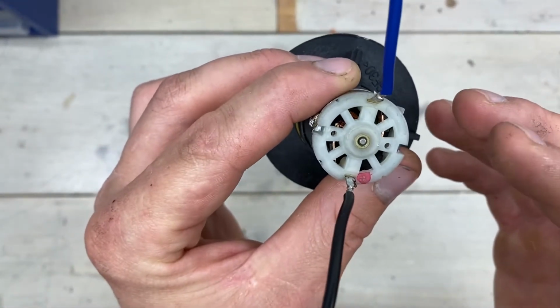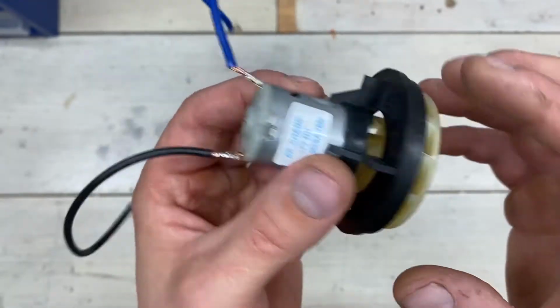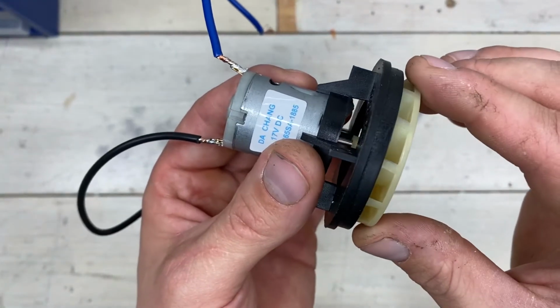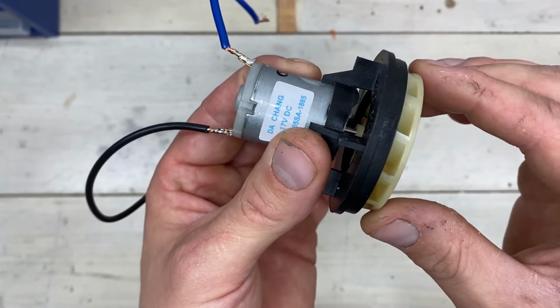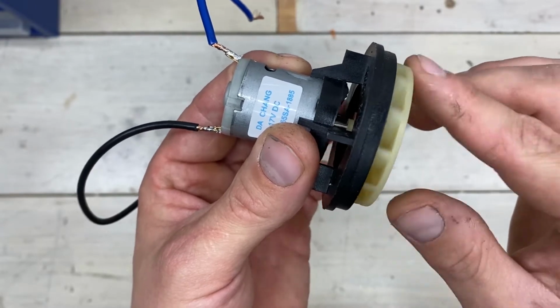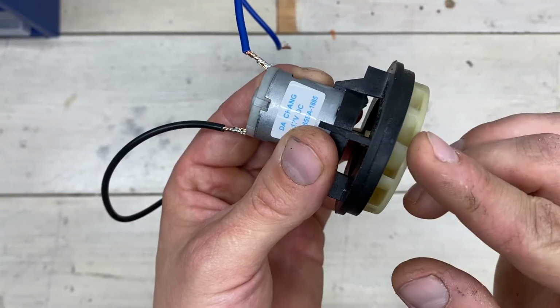And this actually serves to swap which of the coils are energized. Which means that we energize two coils, it moves a bit. We energize the next coils, it moves another bit. We energize the next coils, it moves a bit more, and so on and so forth, until we're back to the first set of coils and we've completed a full revolution.